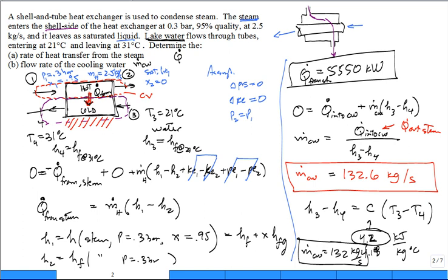Yeah, and you know what? I should have had this subscript changed. It should be 4 minus 3 because it's going out hotter at 4, right? Sorry about that. If you just look at the sign, I had to switch this to H4 minus H3. Sorry about that. 4 minus 3, temperature 4, which is higher than temperature 3. If you did 3 minus 4, you would get a negative answer, and then you'd say, which direction is my heat transfer? Into the cold fluid? It's into the cold fluid.